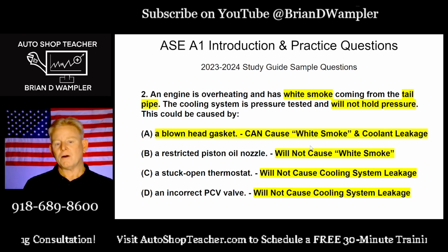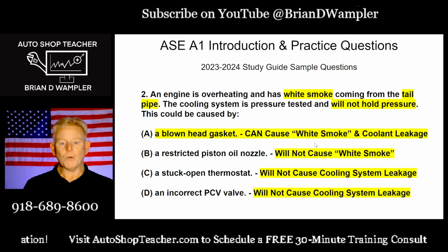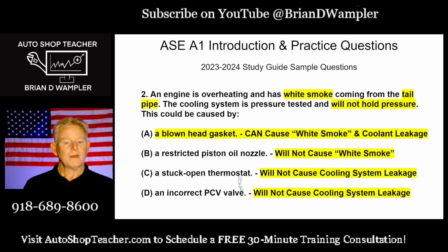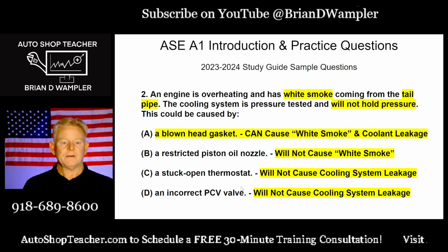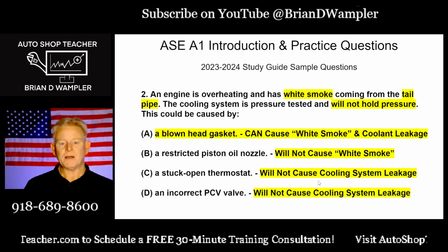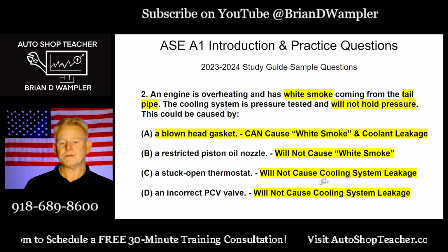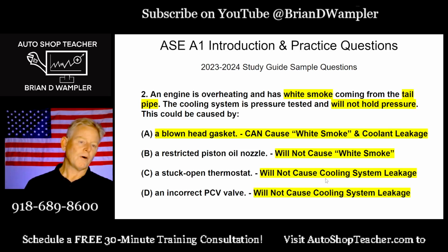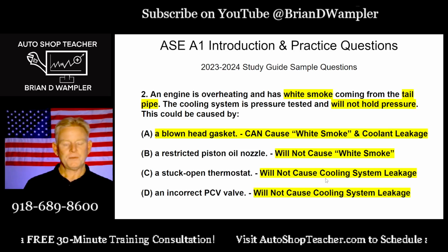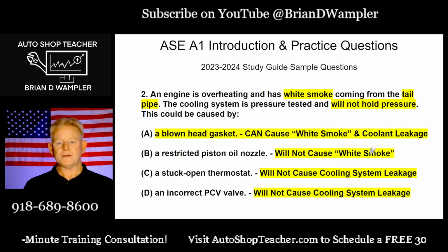But again, it will not cause white smoke. If somehow it was getting oil into combustion, again, it would be that blue smoke. A stuck open thermostat would not cause cooling system leakage. Same with answer B, I didn't mention that. The piston oil nozzle also would not cause cooling system leakage. Again, remember all of the information you're provided with the question. Incorrect PCV valve, again, also would not cause coolant system leakage.